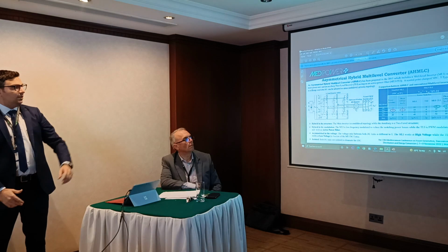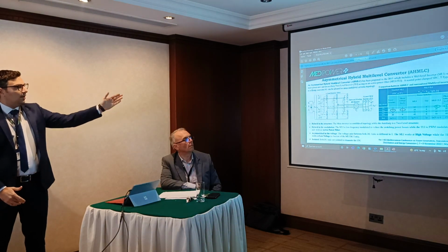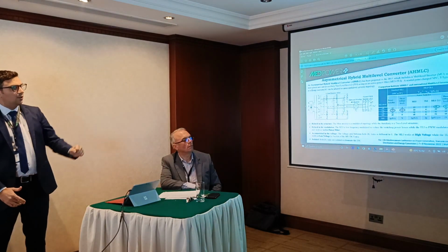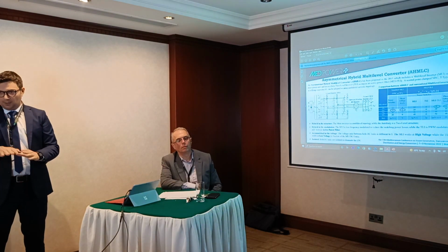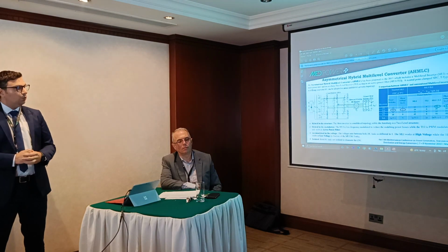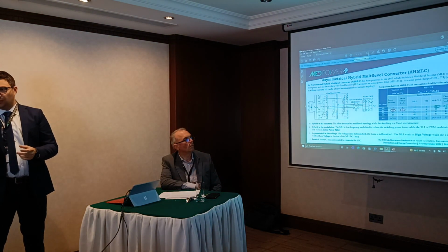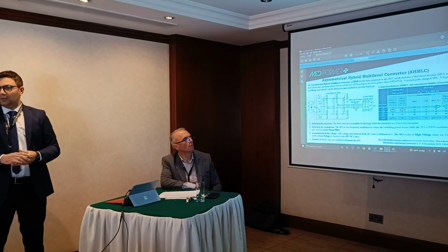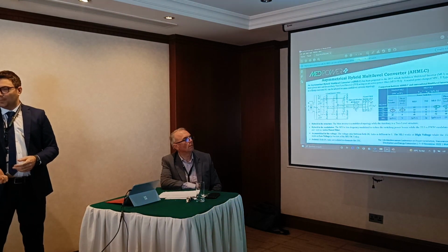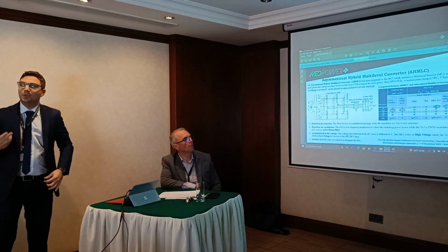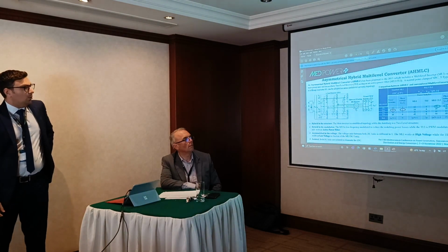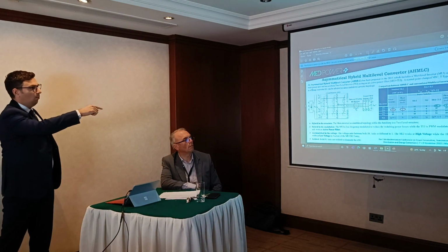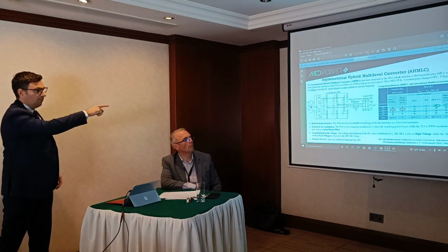The main feature of this system is that it is asymmetrical and hybrid, because the main multilevel converter works at a high voltage but a low frequency, in order to reduce the switching frequency. On the other side, the two-level converter works at low voltage but high switching frequency, and works as an active power filter in order to eliminate all low order harmonics generated by the first converter.